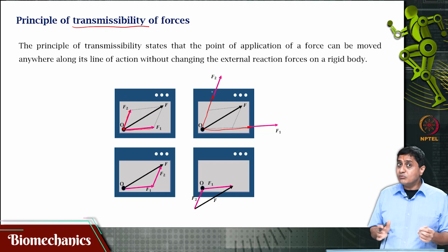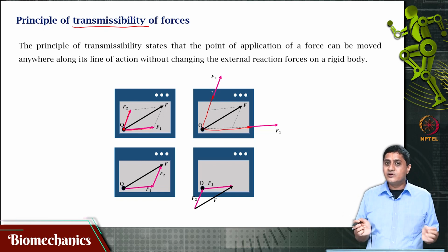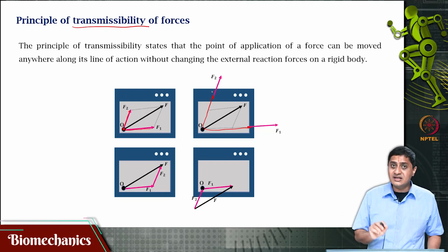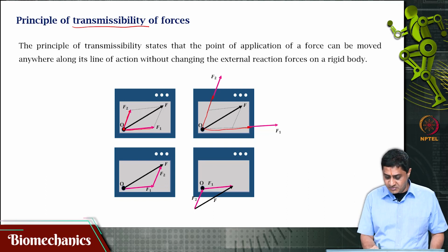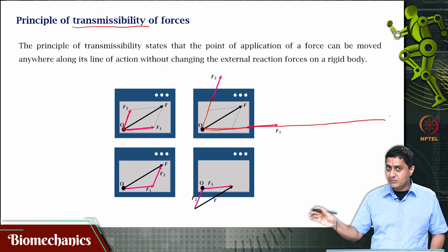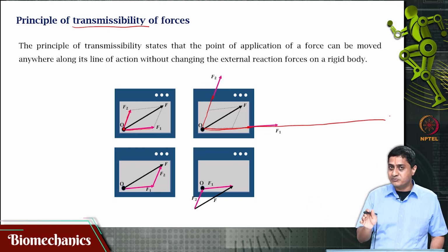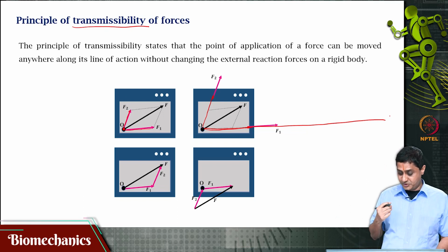Important, you cannot move it anywhere you want. You can only move it along the line of action of that force. So for F1 it can be moved along this line infinitely anywhere, but I cannot move it to any other point. Okay, important to remember that.